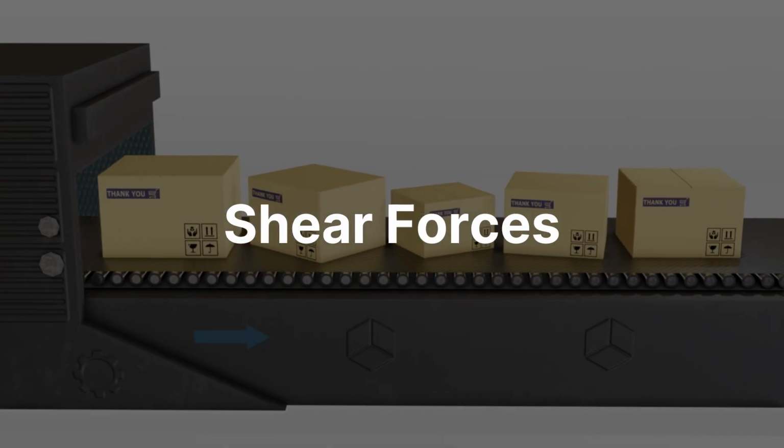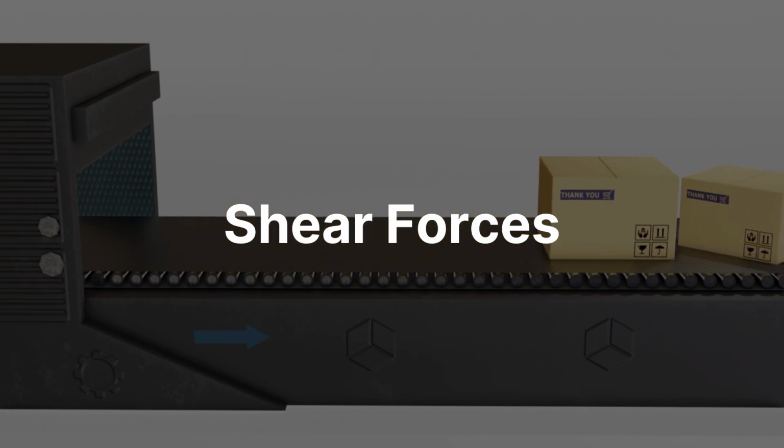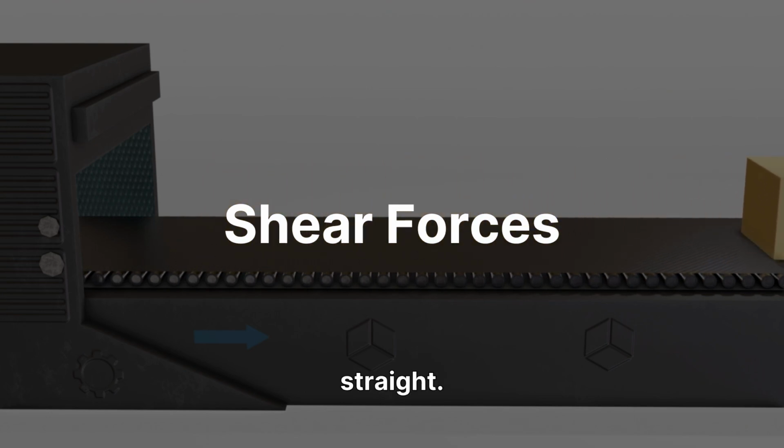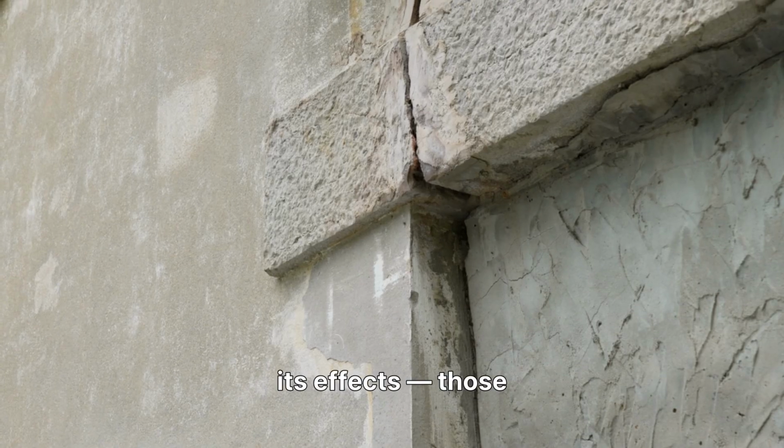Then comes shear. When a beam carries load, that vertical force has to travel down to the supports, and it doesn't go straight. It moves diagonally, forming a kind of internal truss made of compression and tension zones. This diagonal force flow is what we call shear. You can even see its effects.